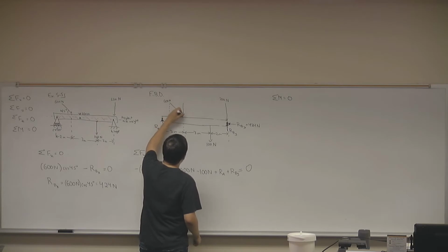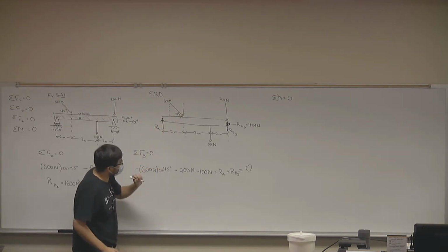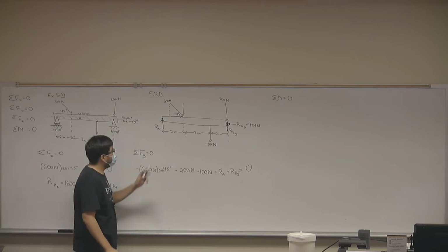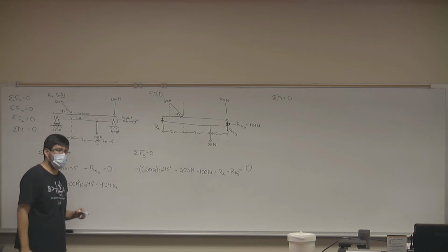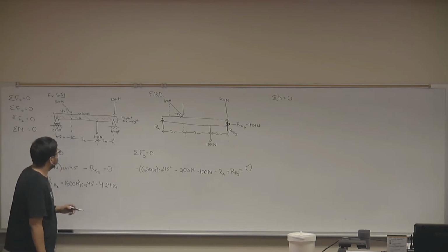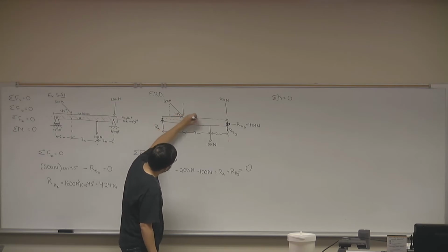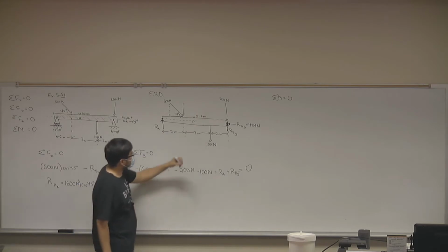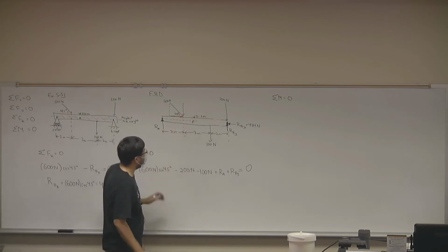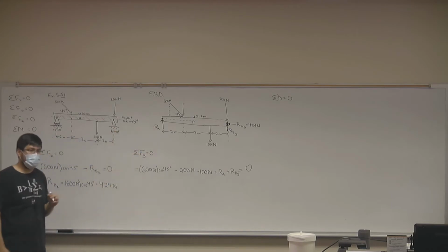So I'm going to draw my Y component here. And let's go ahead and find our moments. I actually realized something. Looking at this free body diagram, we forgot one distance here. Can you see it? What distance did I forget, Riley? The distance from the middle of the beam. Yep. From the center of the beam, 0.2 meters or 20 centimeters, okay? Very important that we caught this, right? Because again, I should be able to solve this problem without looking back at the diagram, okay?